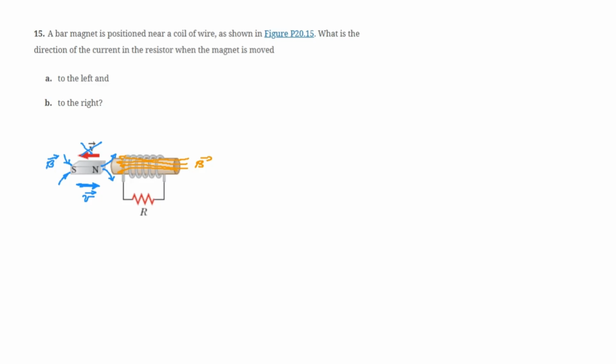Now, use the right-hand rule, wrap your four fingers around the solenoid or coil, and your thumb is in the direction of the magnetic field that the current needs to induce, and you will see how the current now needs to follow this other path.